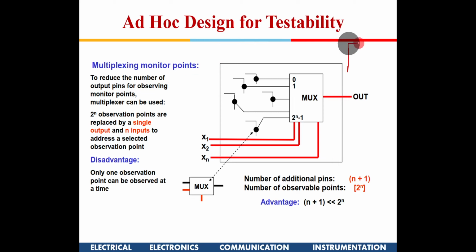once a chip is fabricated, you have to select the chip before sending for fab. So the number of physical pins will be limited, right? It won't have an infinite number. So you can't keep bringing all the intermediary block outputs to individual, unique pins. It will require a large number of pins.